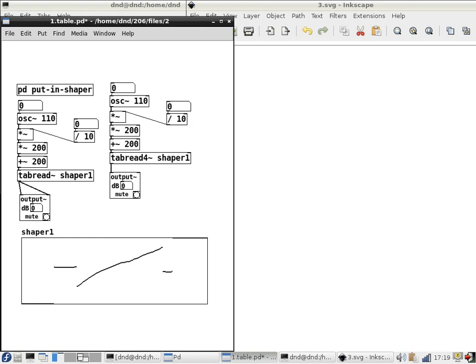So the table is not something that you really want to change in a continuous way in time, because you would have to compute all the points of the table, and then it would even take the time to try to draw it again, and that would be kind of ugly. So a bad way to change something that you're doing by using a wavetable would be to just recompute the entire wavetable. Especially considering that if the table changes discontinuously, the sound changes discontinuously too, right?